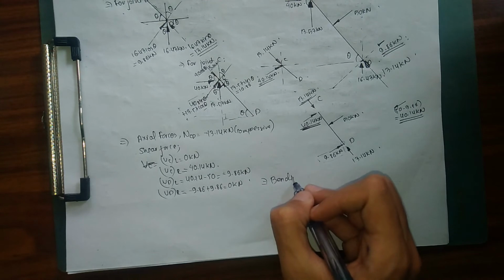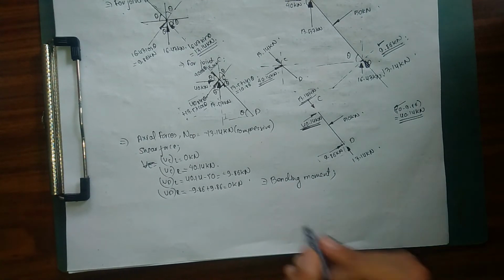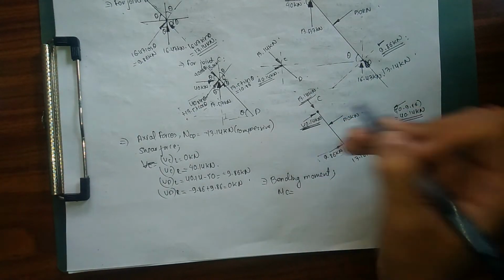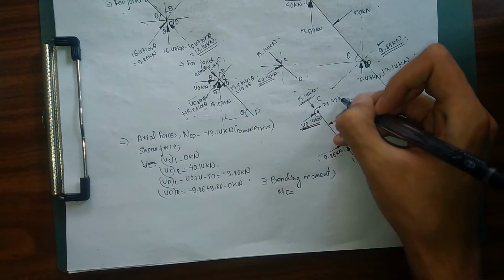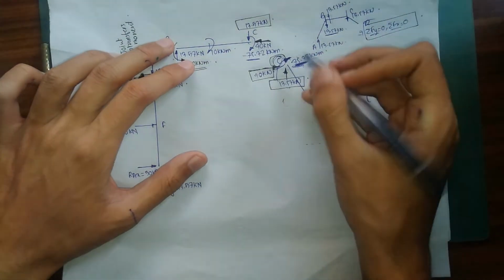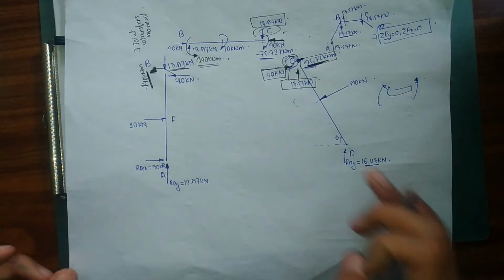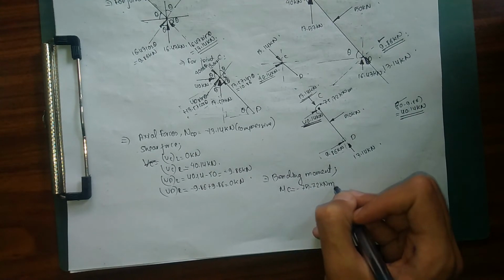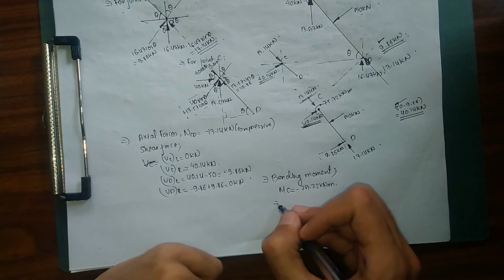In order to calculate our bending moment, we can take our shortened section, or we can do this directly as well. So let me just do it directly. We are going to take our bending moment at our point C. So here is our 75.72 kN. As I explained before, for our bending moment, we have the 75.72 from our joint C, which is transferred over for our member CD. So for our C, we are going to have this moment only, negative 75.72.